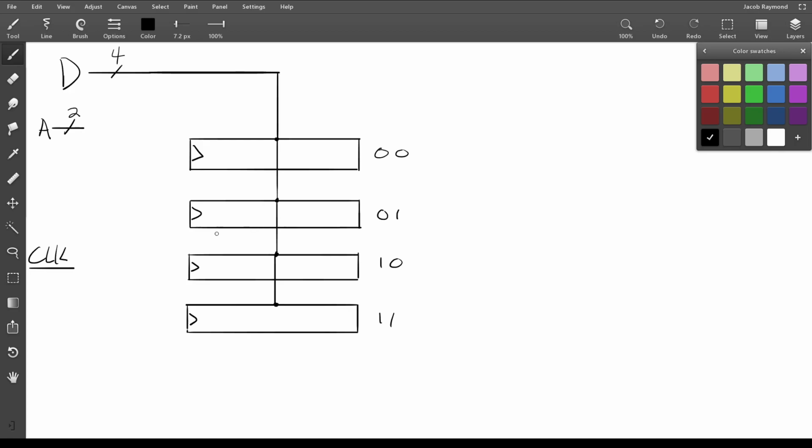And so instead we can just have a clock, and we'll say when the clock is 0, don't do anything. Just sit there and do not actually write anything. But when the clock is 1, it'll actually write something. And so now, when this is 0, we essentially could send zeros to all of these, right? Just because this is 0, and that will just maintain the state, not update anything. And then when the clock is a 1, well, then we want to specifically route the 1 to one of these locations here. So how do we do that?